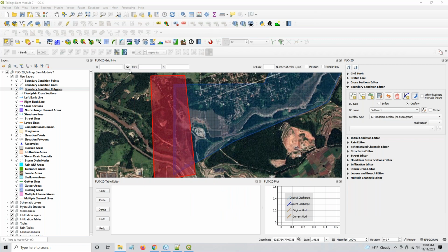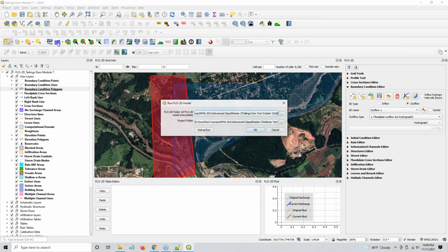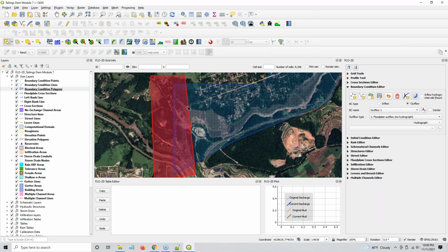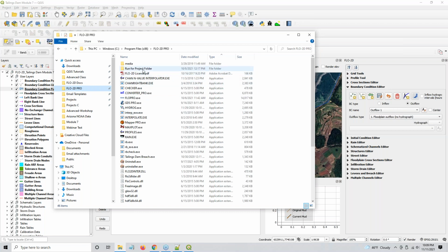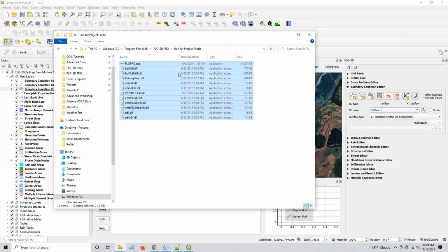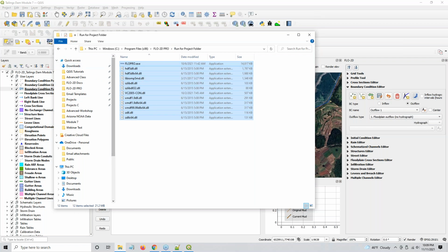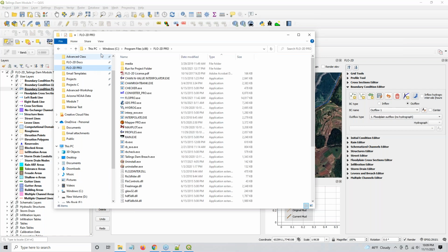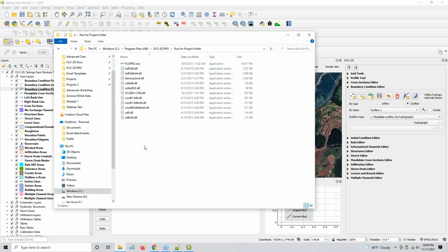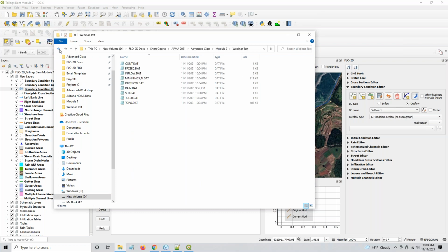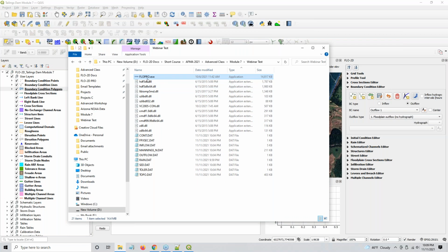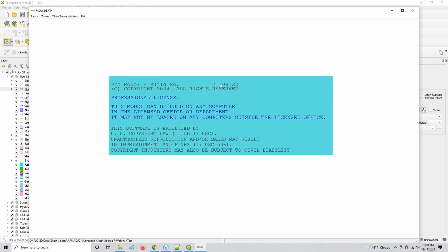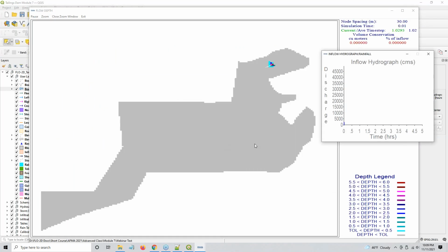Now, this is something that just started happening because JJ and Noemi were testing the model, and there is another wait command in the engine. So if you run your engine from here, it's going to lock your map up, which you may not want to happen. So for the time being, until we fix that, which should be fixed by the end of the week, I recommend that you use the run for project folder, copy your engine straight out of there, and put it back into the project folder. Again, that was C drive, Program Files x86, Flow2D Pro, run for project. Control A will select it, Control C will copy it, and then back in the project folder, Control V, and then you can run that from here, and that way you don't lock up your map. Again, if you're going to be running mud flow, tailings dam, sediment transport, or any kind of breach, you have to have build 21.